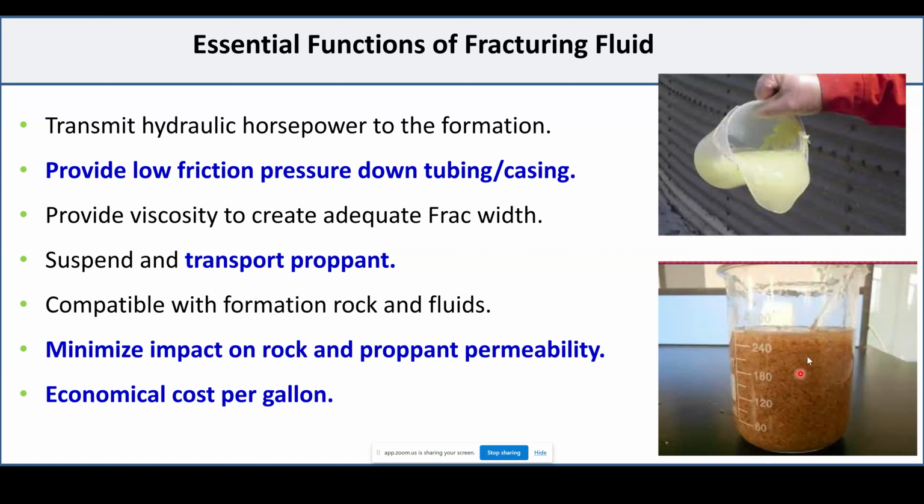So when you're injecting this fluid, the sand will go with the fluid and will not settle, and will fill the whole frac that you created, keeping a good width. When you break the fluid and the frac closes, the sand will stay downhole, covering the whole area.